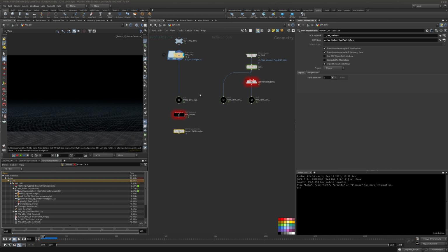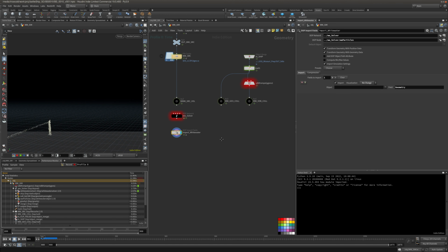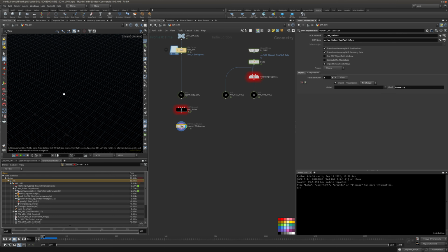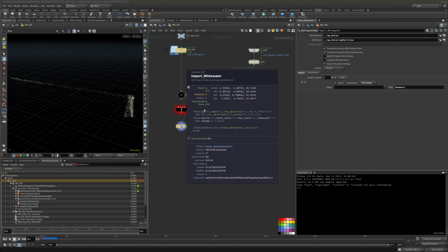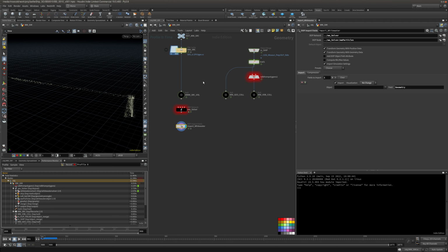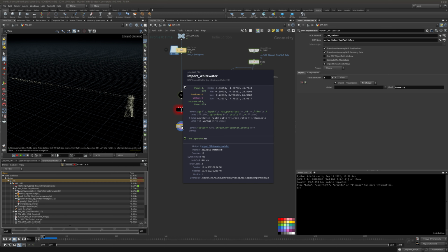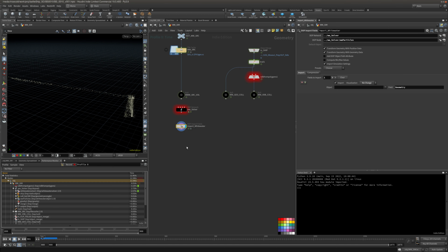Okay. Now, what do I want to come out from here? So if I select this guy, oh, sorry, here you can select particles. By default, that's just geometry. I'm not going to use any of this here. I'm just going to go frame forward. So put some stuff out. Okay. Now, this part is, I think, quite important and mostly skipped. It's very important to do a good cleanup. So let's make sure that we get rid of anything we don't need. Okay, so drop in an attribute delete.